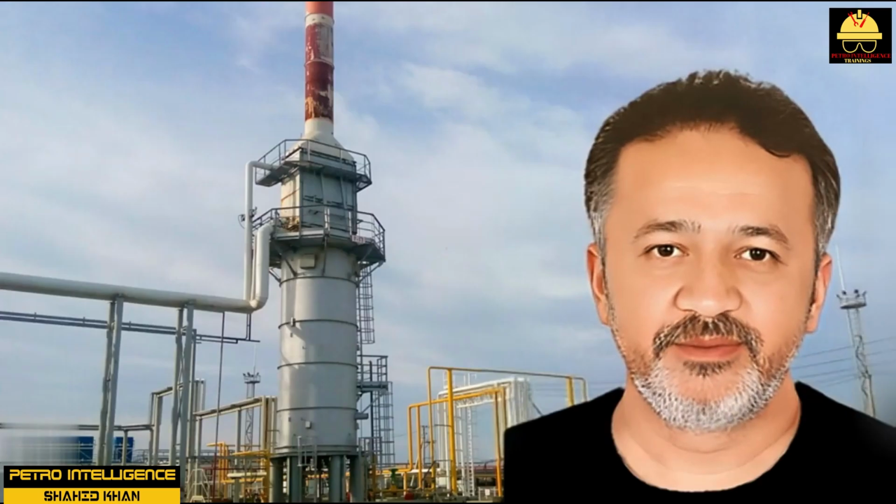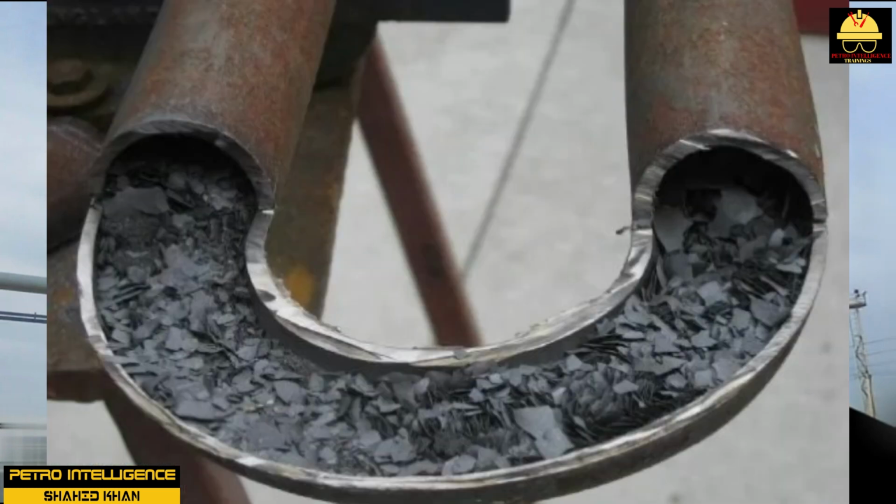Plugged burner. Plugged burner tips tend to make the flame pattern appear erratic as it shoots up and out toward a tube instead of up the firebox. Coke buildup. A certain amount of coking occurs naturally over a period of time inside the radiant tube section. Shutting down the furnace and injecting superheated steam can clean up this problem.